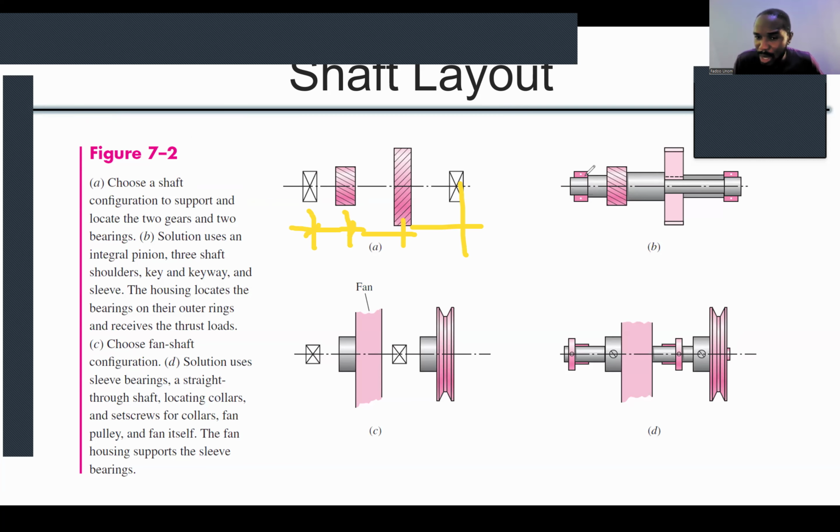So when I'm installing my bearing, I fit it on that shaft and push it axially until it stops at the shoulder. Then I have a slightly bigger diameter there that provides the shoulder for the bearing to stop, but it allows the gear to enter and go until I stop at that point.